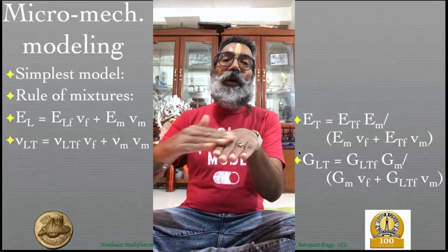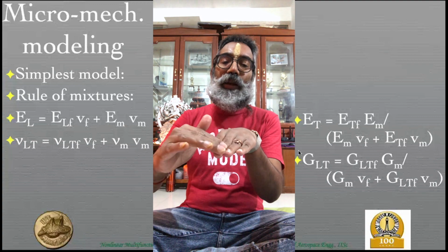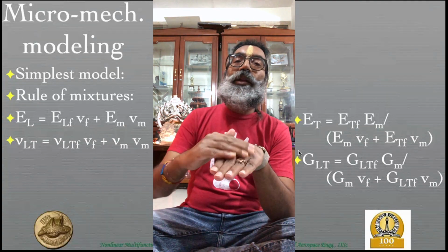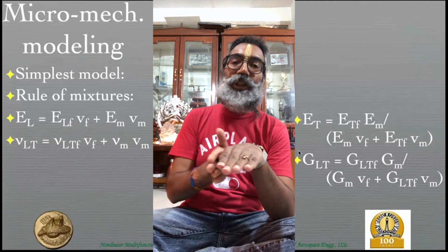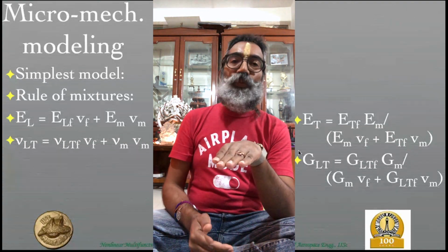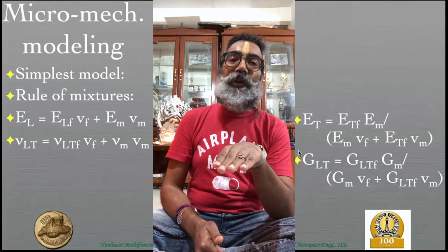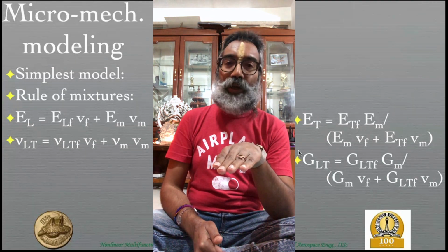So this particular plane is the LT plane, in which you are basically having L and T directions, and therefore the shear in that direction, which is basically the in-plane shear for a plate, that modulus is going to be given by GLT, and in general it can be different from the G along other directions.